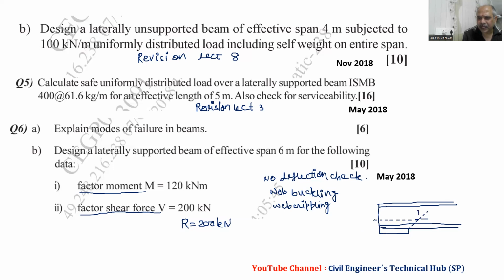And this value we will get as, this is B. So we have this as B plus 2.5 into thickness of flange plus root radius. So you can go to web buckling and then you will come to know. So this height, if you see, will be TF plus R1, and horizontal becomes 2.5 because we have a slope of 2.5.